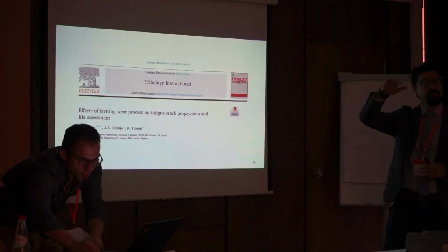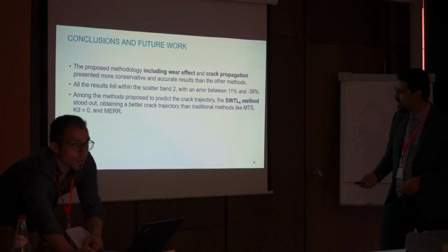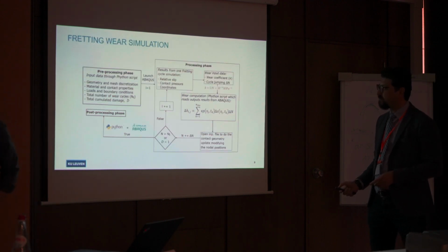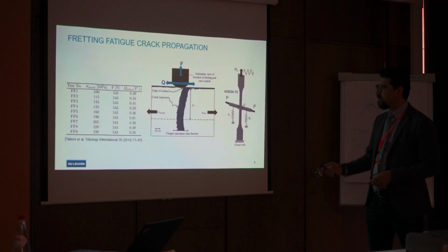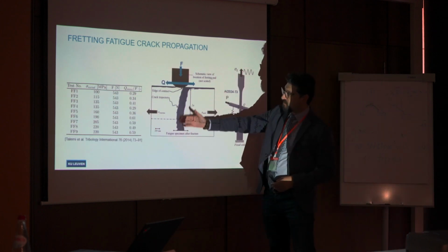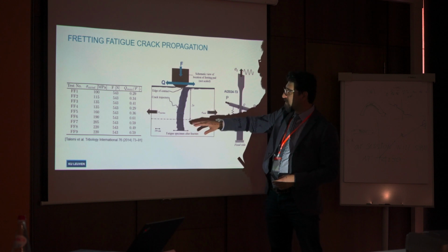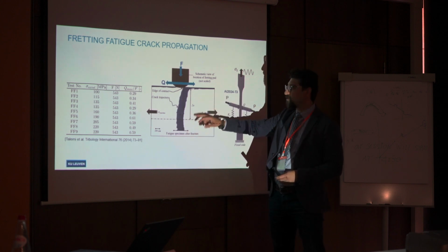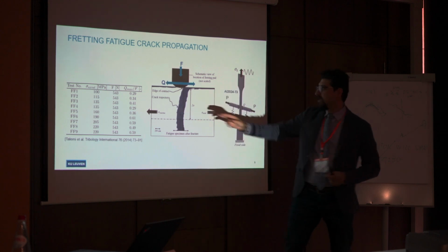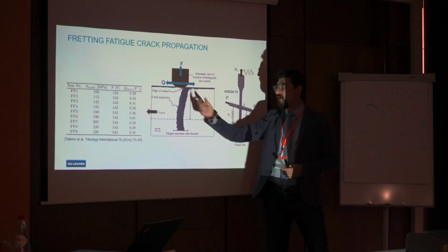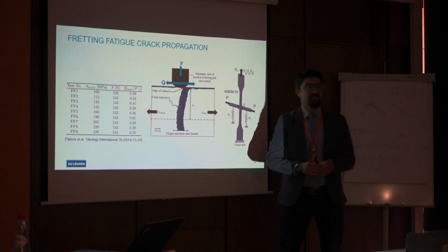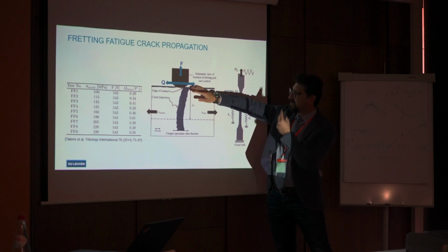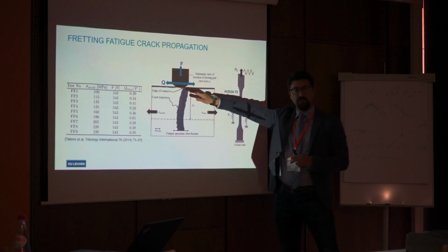So you were talking about the experimental observation here. This is the important part you're focusing on. It's 2 times the contact area, where a is the semi-contact width. From here to here, the crack is governed a lot by the combined effect of normal load and tangential load.